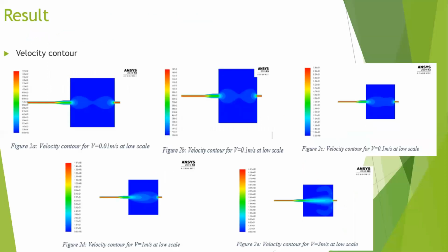In regard to the velocity contour, we have 5 figures illustrating the 5 different inlet velocities. As you can see, the fluid proceeds along the geometry with changes in area. They have different contours. For instance, in section 4, where the area is largest, the fluid is evidently moving most slowly in that section. Then, due to being squeezed down, the fluid accelerates in the final section.